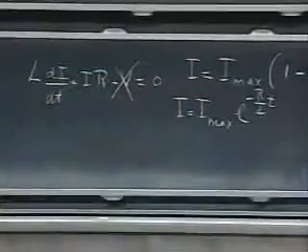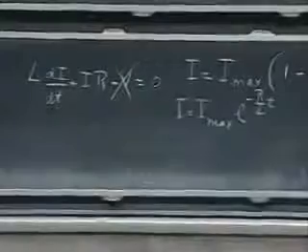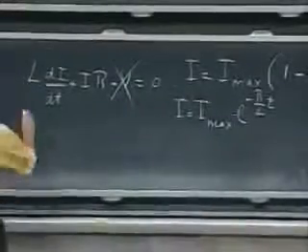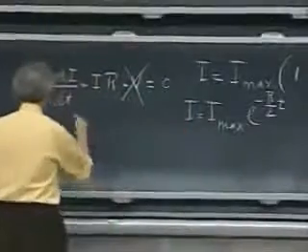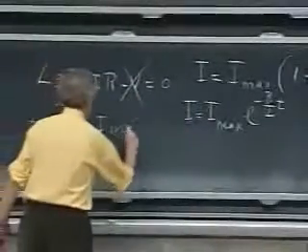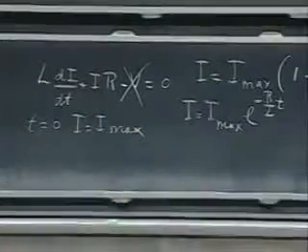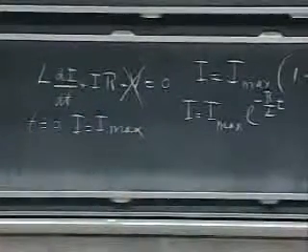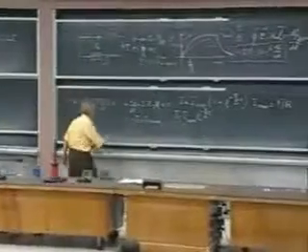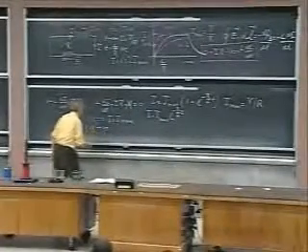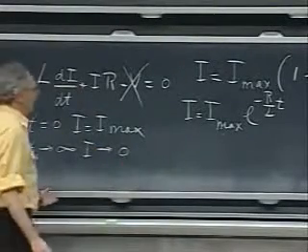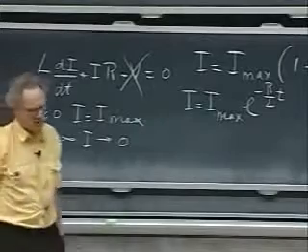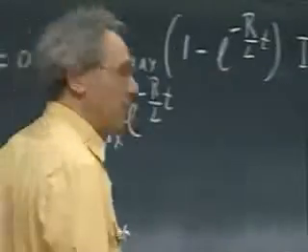And that exactly has all the quantities that you want it to have. Because notice that at t equals 0, when you put in t equals 0, the current is indeed maximum. And that's what you require. That's the moment that you make that capital V 0, the current was still running. But notice that when t goes to infinity, you wait long enough, that indeed the current goes to 0. And if you wait L over R seconds, then you are down to about 37% of your maximum current.